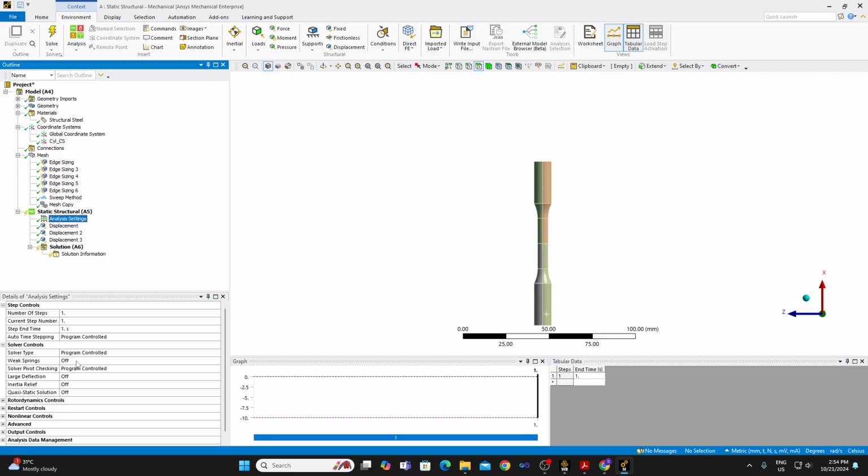because in the finite element method, even if there is no force in a given direction, you still need to have a rigid body constraint for the object in the same direction, and that applies to both translational and rotational degrees of freedom. Otherwise mathematically it cannot solve the problem, because zero force can yield an arbitrary amount of deformation in a given direction. So weak springs can take care of that in case that constraint is not there. But if you have properly constrained the problem like we have, then you should skip the weak springs. That minimizes the error in your solution. Does that make sense?